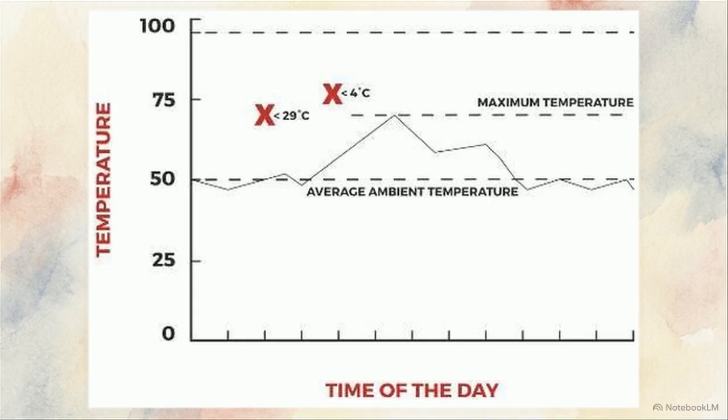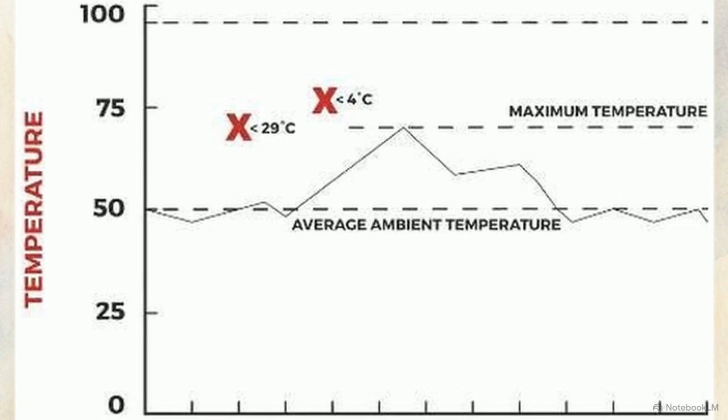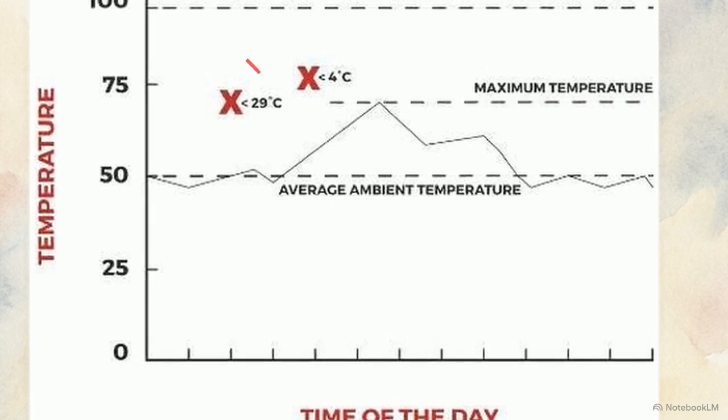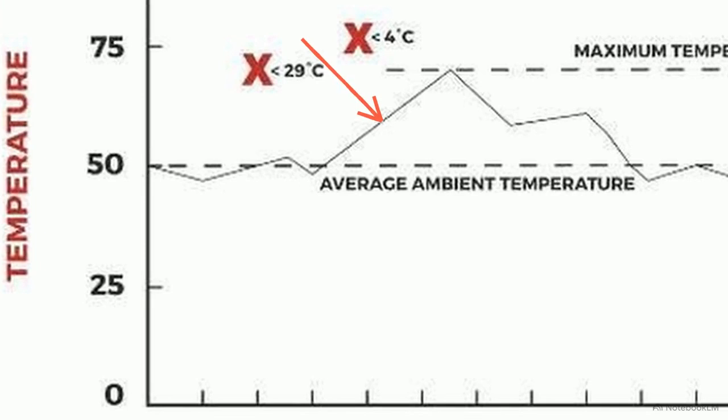This chart displays temperature thresholds for heat devices. To prevent false positives, a fixed device's static response must trigger at no less than 29 degrees Celsius above average ambient temperature. Looking at the curve slope differentiates detector types. A fixed detector waits for that specific threshold. A rate-of-rise detector triggers upon a rapid temperature spike, reacting to the fire's sudden slope rather than gradual warming.